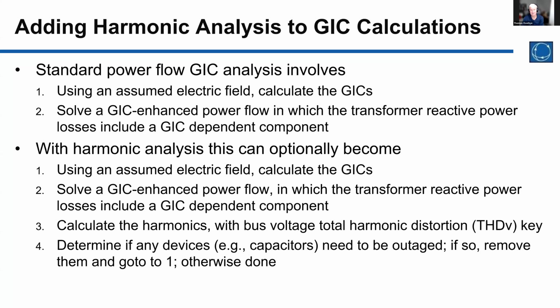It's essentially solving a DC circuit. And then we look at the positive sequence impacts of those currents and we represent them in the power flow, then we solve the power flow. And primarily this involves getting increased reactive power loading on your transformers.